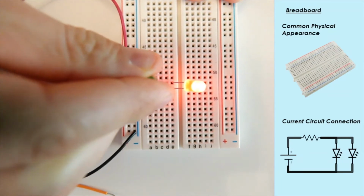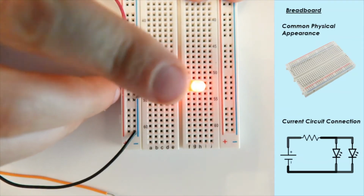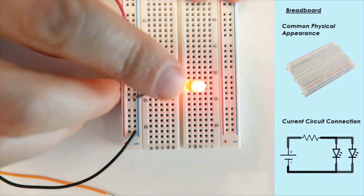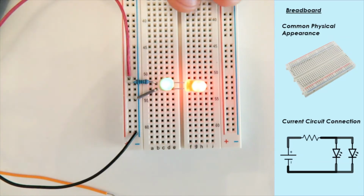So if I go ahead and shove that in there, you should see that that is now lit up, just because they're sharing the same thing. So those two LEDs are now in parallel with one another. Okay, and that is breadboarding basics.